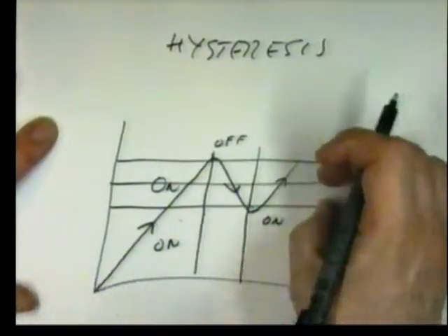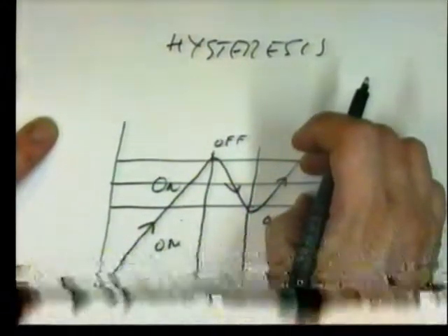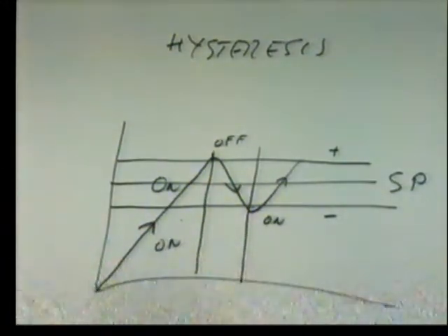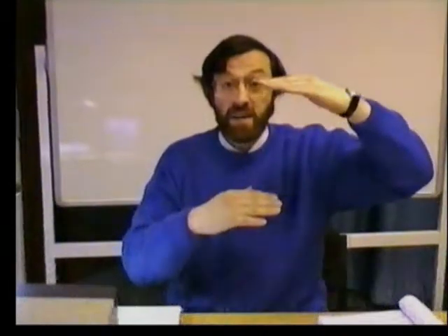And what we do is effectively we're widening the set point, and as I showed you earlier, there is a relationship between the amplitude of oscillation and the frequency. If you want to slow down the frequency of oscillation, you need to widen the amplitude. And if the inherent response time won't do that for you, by adding a hysteresis band, you force the system to oscillate over a wider band, and that will happen at a slower frequency, and your system will survive.